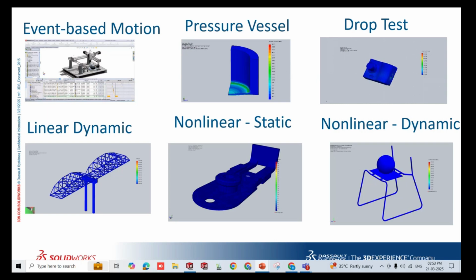Next step is pressure vessel. SolidWorks Simulation provides a specialized pressure vessel design study type. This allows you to combine the results of multiple static studies, which is essential for evaluating pressure vessels. This feature is useful for complying with design codes that require the combination of various loads.